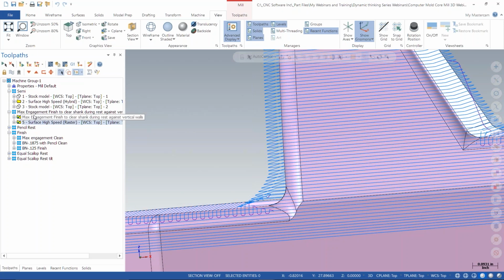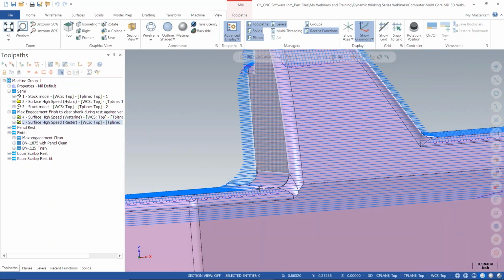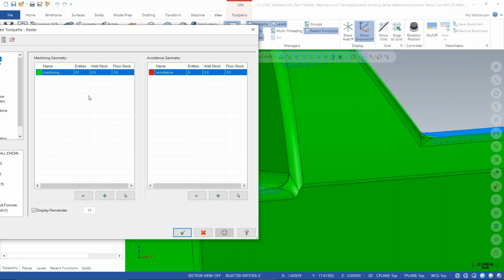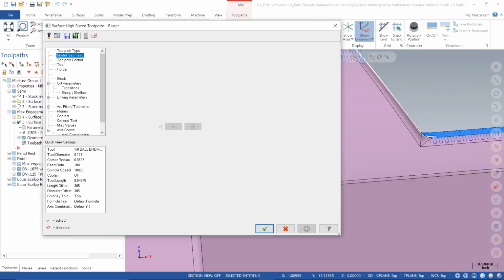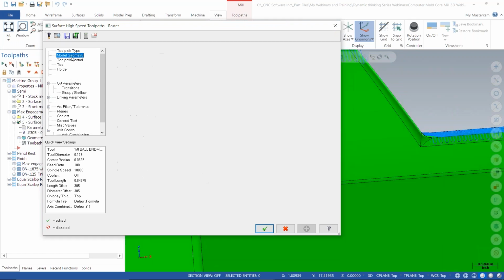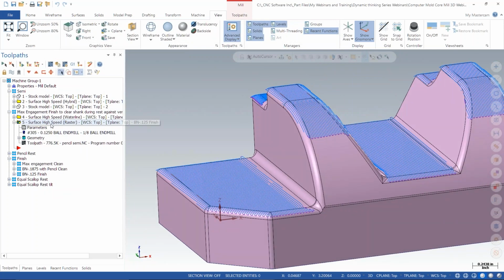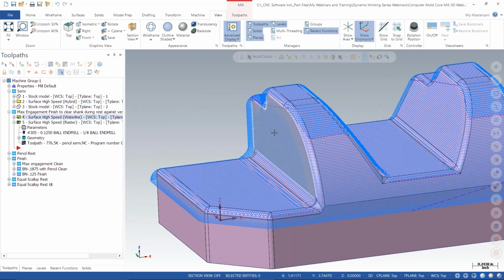That was max stock engagement. And I wrote this 0 stock to leave toolpath, so it just left material here, 0 stock to leave. I turned on max stock engagement like the last example on this page, so I was able to rip the water line. I let it dig into the stock 20 thou, but I was machining to 0. So that part is basically finished on the walls, and everywhere else the corner's heavy.